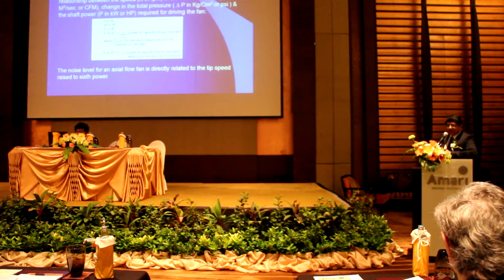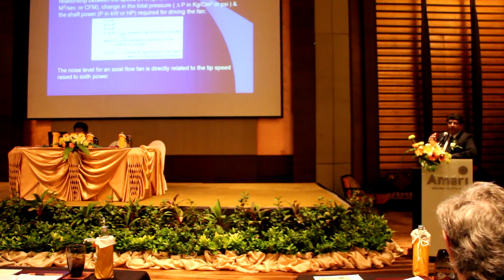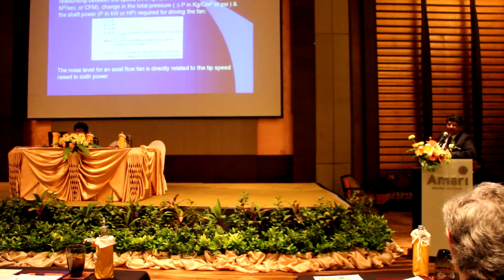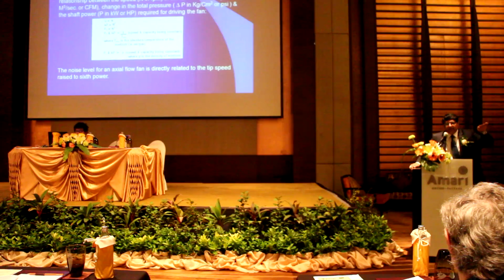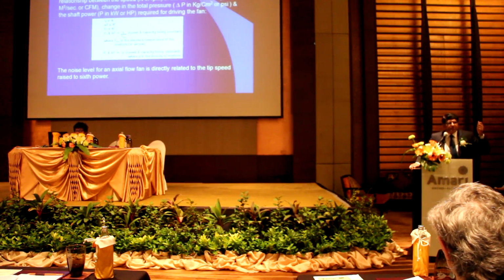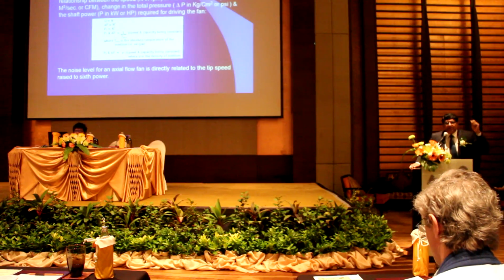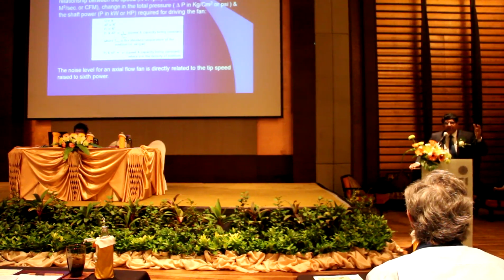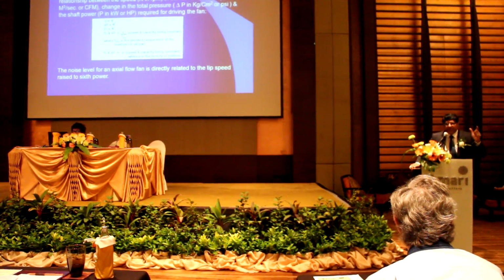So other than that, you find that some of these aerofoils have a limitation called stalling, which most operation people get into. What they do is, if the fans are operating at a particular angle of setting, they say, oh, we need more airflow and we seem to have the motor capacity, so why don't we go on pitching up the blade angles? Once you go on pitching up the blade angles, there is something called stalling that occurs in these blades, depending on the blade design.